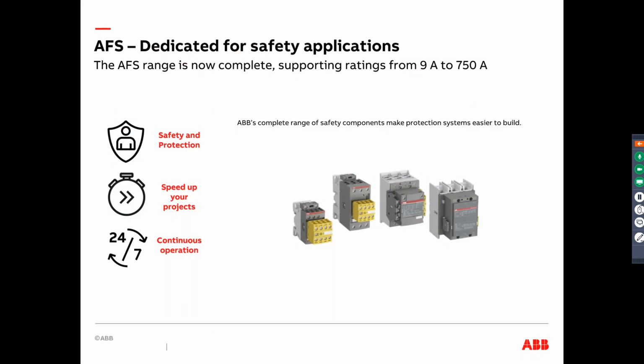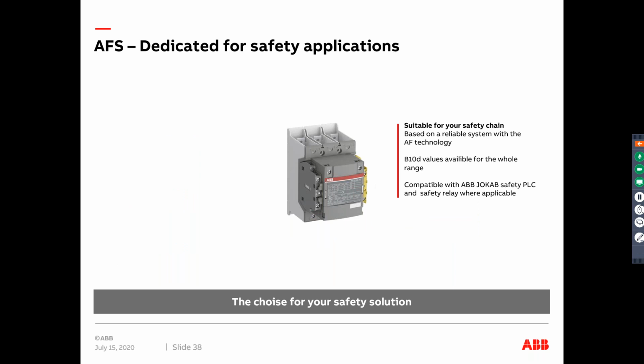We have contactors for safety applications as well. They were launched somewhere last year, and they go from 9 amperes to 750 amperes. They use the same technology as our AF contactors. We have all the failure rates available, which we determined during testing. They are even compatible with our safety PLCs.